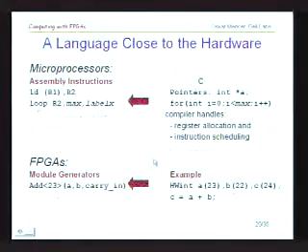So now, if we look at what I'm trying to do here, we look at what C does to a microprocessor. You have assembly instructions or opcodes, and here comes C and says, I'm providing a higher level interface, a language that has the same types that my architecture supports, easy mapping from the language down to assembly, but I'm not going to keep, for example, the number of registers in my language. I'm not going to keep the actual limitations of my architecture that I have. I'm going to let the compiler do register allocation and scheduling, which is something that I can easily do in a compiler and that is tedious to do for the programmer.